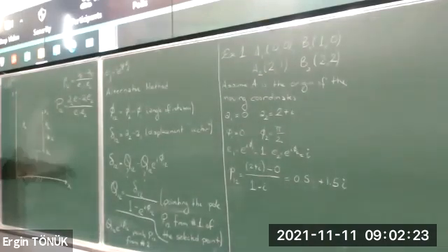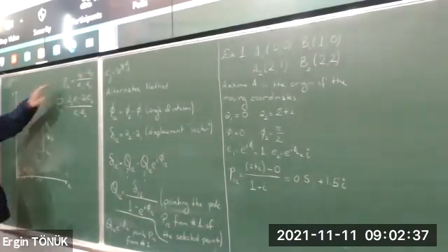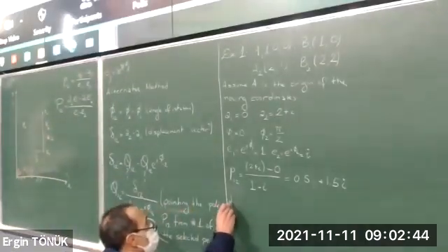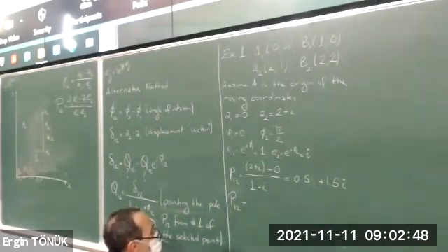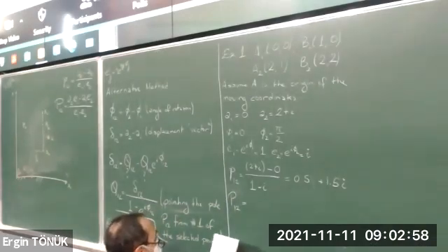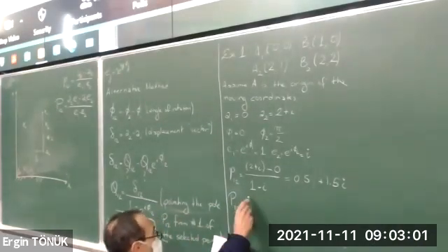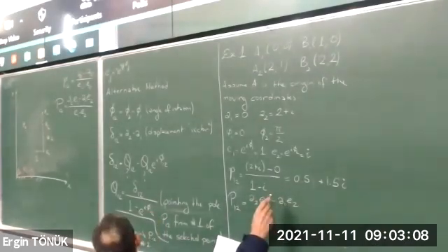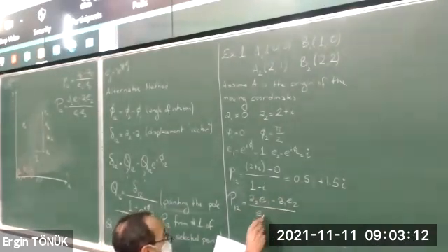So any questions on position of the pole in the moving coordinates? It's the only coincident point in 2 positions. This was how we derived this equation. Okay. Now, for capital P12, which is the coordinates of the pole relative to the fixed coordinate system, it is A2 E1 minus A1 E2, hope this is correct, yes, over E1 minus E2.